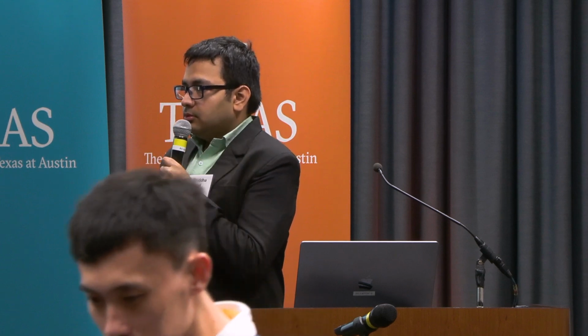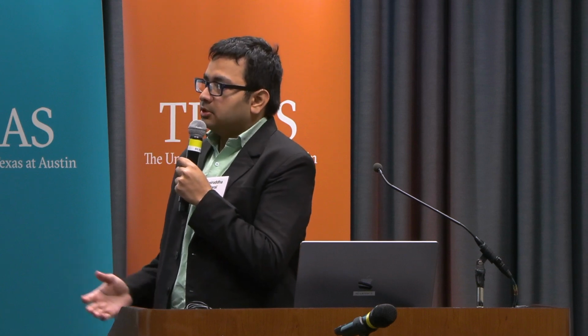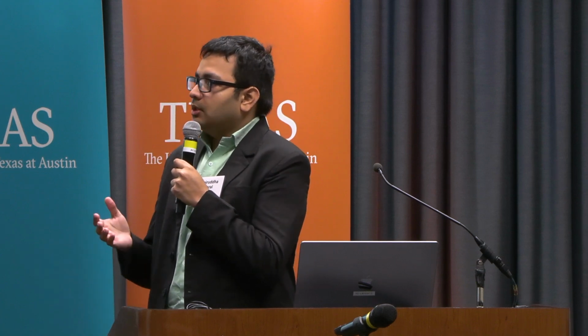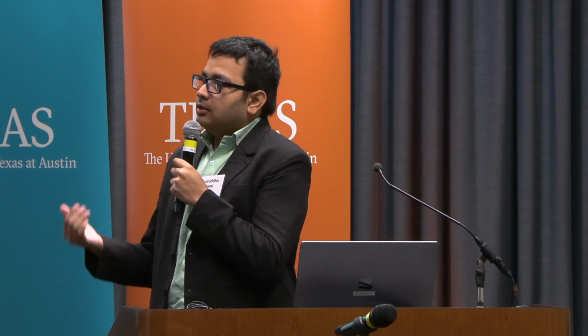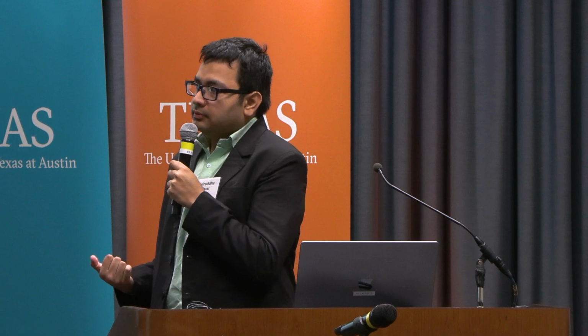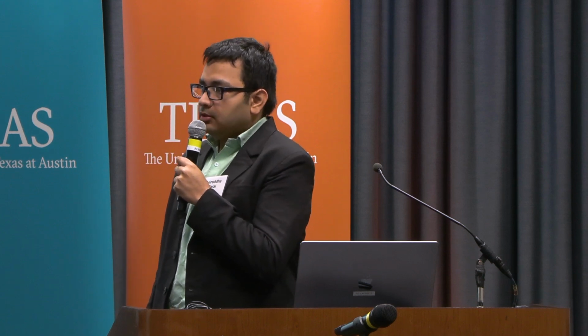Very interesting question. For now, we are just using 2 waste glasses. We are collaborating with a company that already does some of the separation of the solar panels. From them, we get the glass cullets, and they provide it at a size of roughly 2 millimeter. Right now in the lab, we are grinding it down to below 45 micron. In terms of using it for pavement, of course, you can use it as a cement replacement for pavement applications. If you are from the pavement community, I'd be happy to chat with you about it.